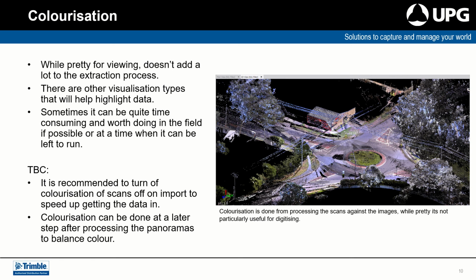Colorization in scan data, while looking pretty, doesn't necessarily add a lot to the extraction process. So when looking at data in the office, colorized data can look pretty. It can give you some form of indication of what's going on if you weren't necessarily out in the field to begin with. However, when it comes to extracting the data, there are other tools and processes that can be used. So the colorization step is not necessarily fundamental to the process and can be done at a later stage. It can be done almost at the end in some cases.